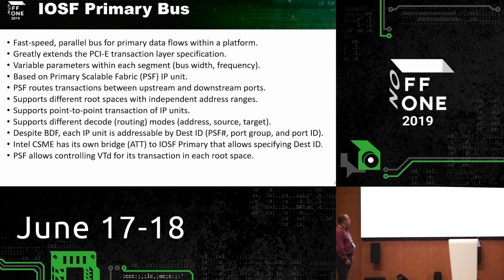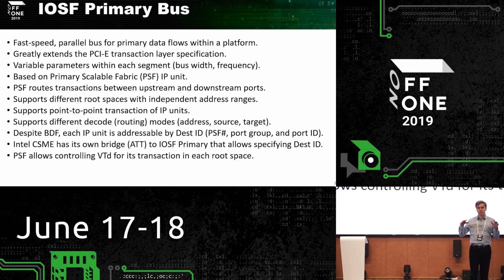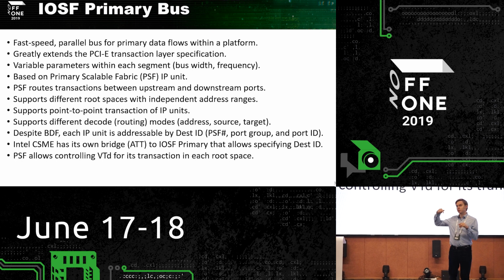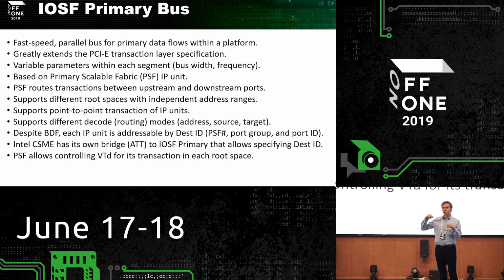Yes, let me just add. I think a good example of how it works runs like this. You have an SPI controller where your BIOS is running. When a CPU turns to this SPI controller for some address, the SPI controller says, okay, good, I've got the CPU coming to me, so I need to take the SPI controller and collect some data from a flash drive.